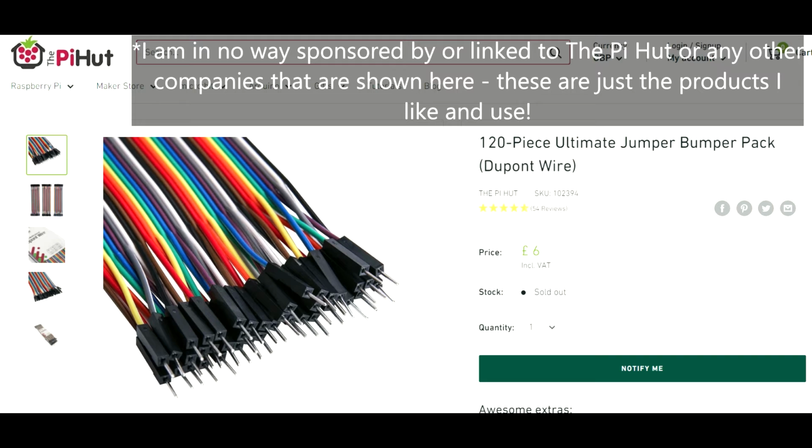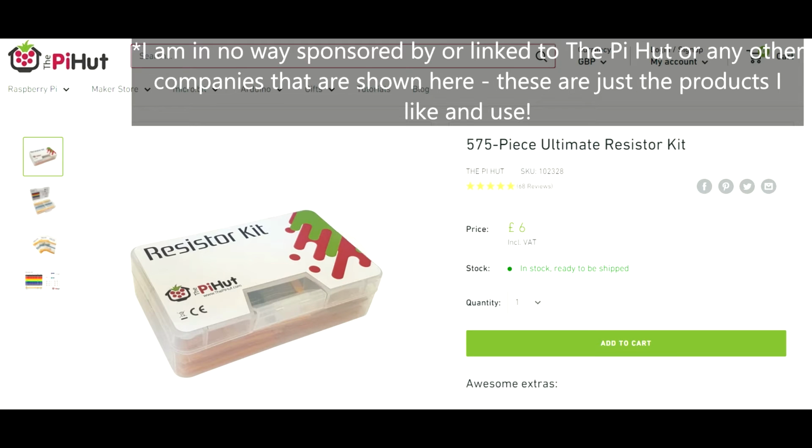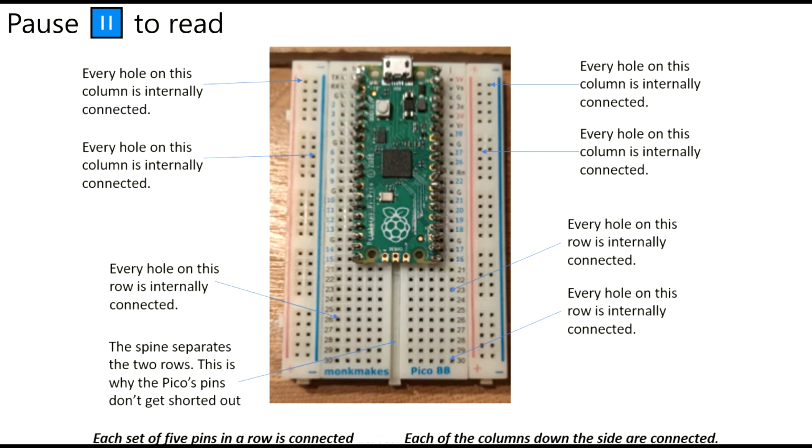You will also now need two male-to-male jumper leads, an LED of your choice. I am using a blue one. You will also need a 330 ohm resistor. If you look at your LED, one of the legs at the bottom is longer than the other one. The longer one is the positive anode and the short leg is the negative cathode.